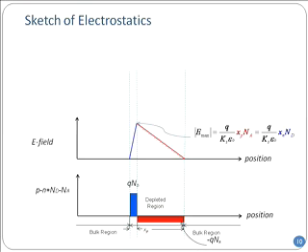And similarly for the red, you will also do the area under the curve for the red, and you can see how much is the area under the curve on the red? NA and Xp, right? These two, and you divide by the epsilon in order to get the electric field. So that's the peak electric field that you can easily calculate.